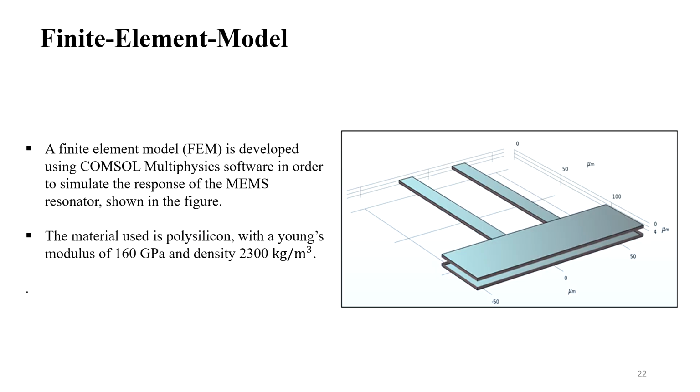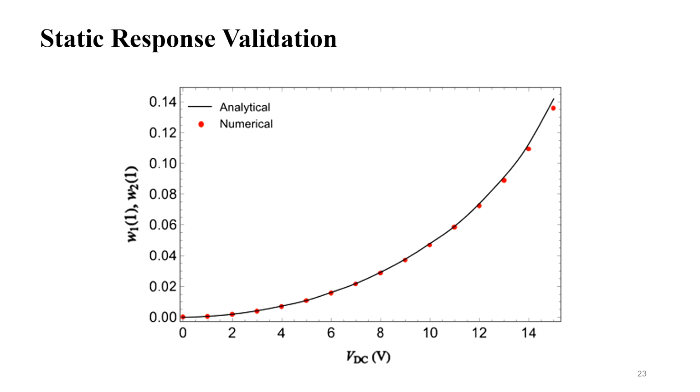To validate our model, we built a finite element model in COMSOL, shown on the right. The material used is polysilicon with a Young's modulus of 160 gigapascal and density of 2300 kg per meter cubed. The numerical static response matched closely with our analytical prediction, as can be seen by this figure.